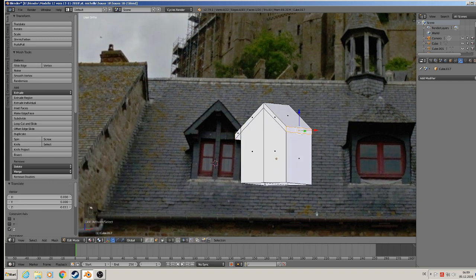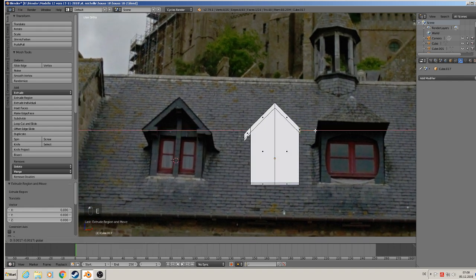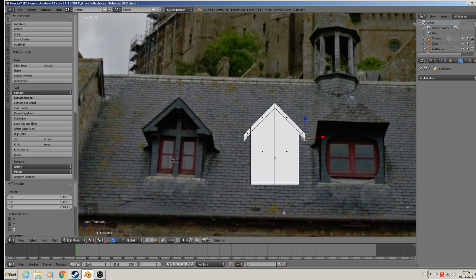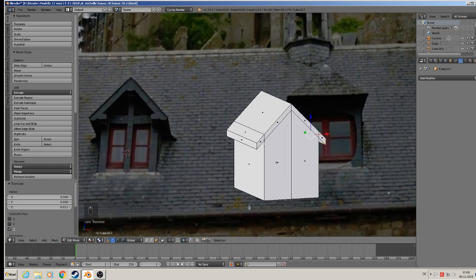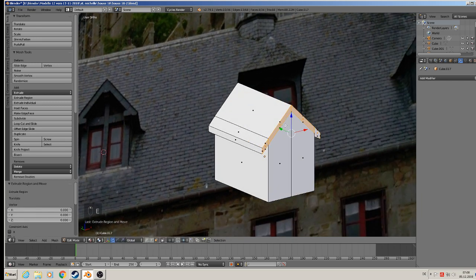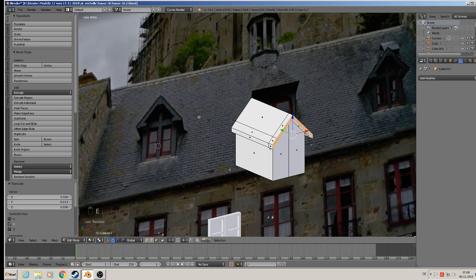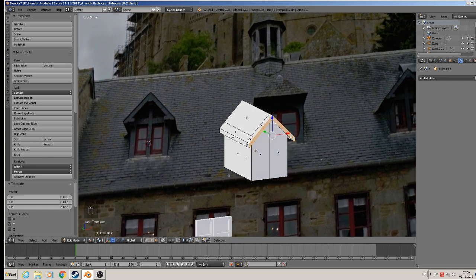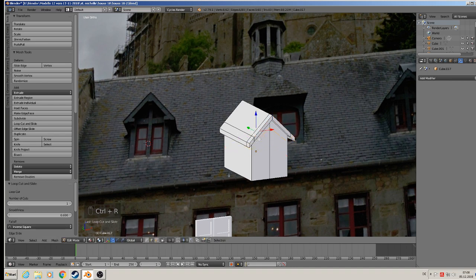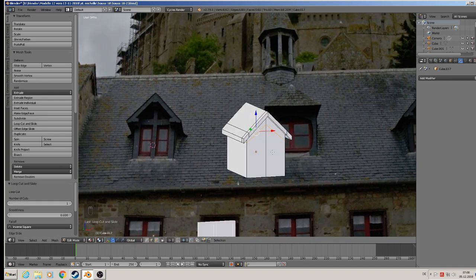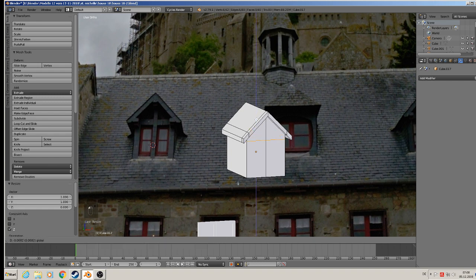Yep. Here the same. Extrude, bring out, and bring down so that it fits with this other one. Then we bring that out at the front, so that it overlaps the rest. So extrude and bring out, so we have that. Good. Then Control R, we need a loop at the top, but it should all be at the same height, so scale set 0. So we have that.